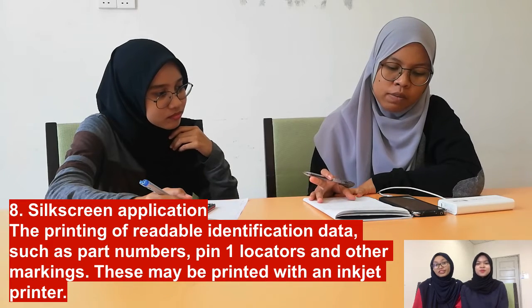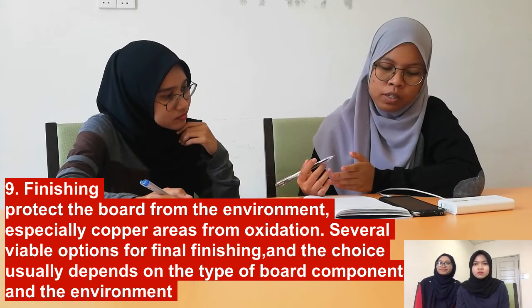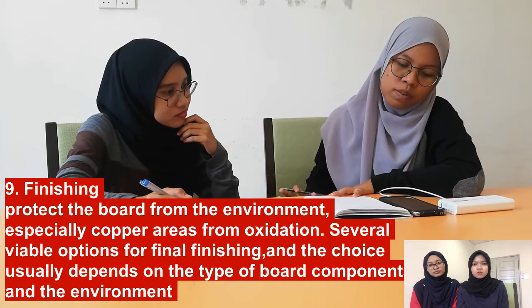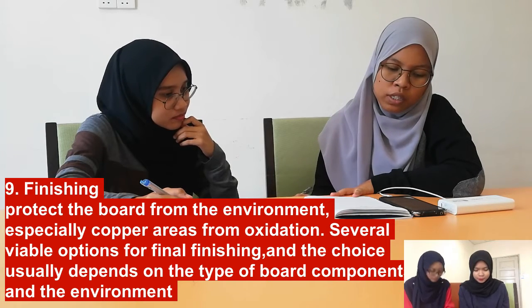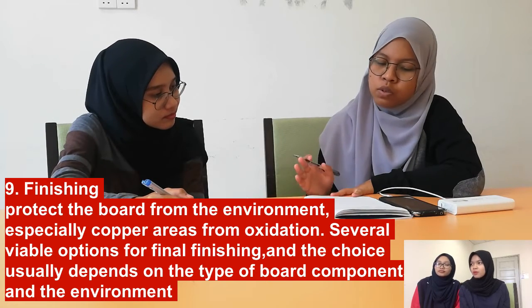The last step is finishing. For this final stage of the process, we need to protect the board from the environment, naturally the copper area that is easy to oxidize. There are several viable options for final finishing, and the choice usually depends on the type of board component and the environment where the PCB is used.